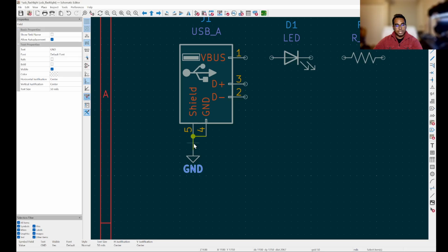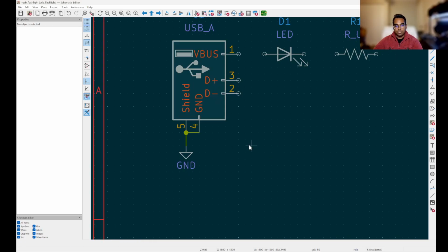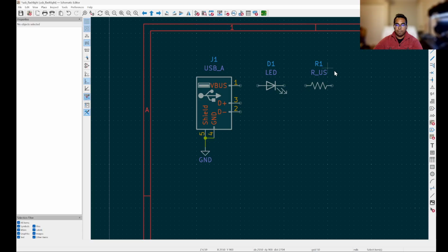Why aren't we just connecting our resistor to that ground with a wire? Well, like I said, it gets really messy very quickly if we have a bunch of different wires for ground, because in a more complex circuit, just about every component needs a ground connection somewhere, or most components will. So by the time we're done with our schematic, we'll have ground wires everywhere, and it becomes really hard to read our schematic.